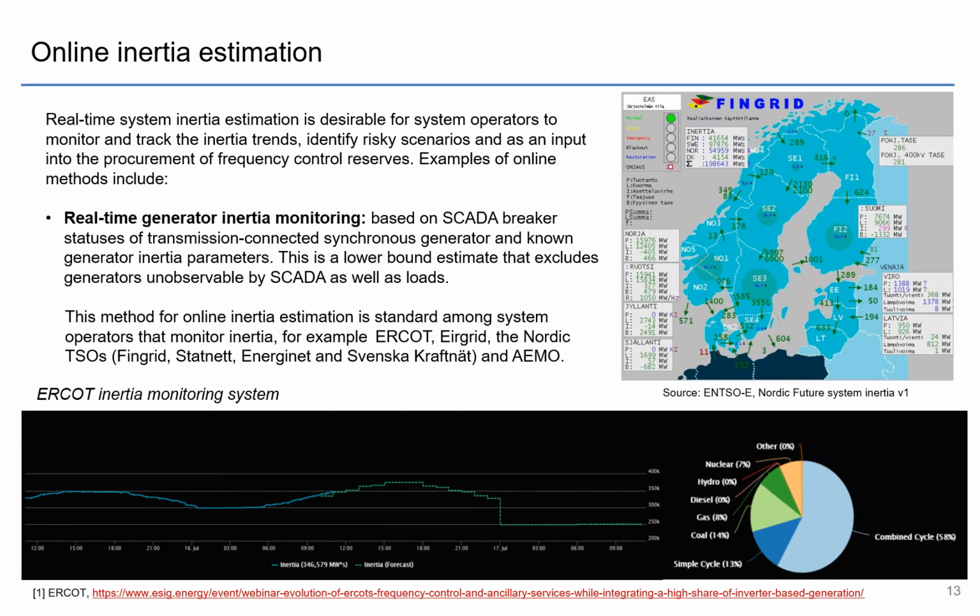The inertia estimation method that's been described using the swing equation is typically used on historical events where you've collected all the data from a generator contingency or a load tripping or an interconnected trip, and you've put all the data together and you're analyzing the event after it has happened.